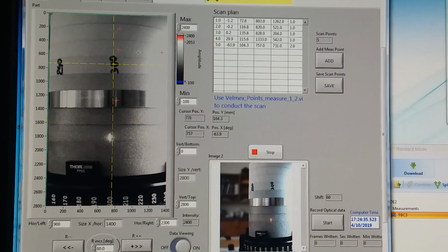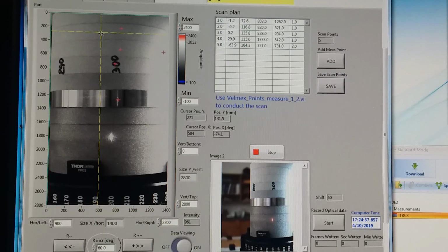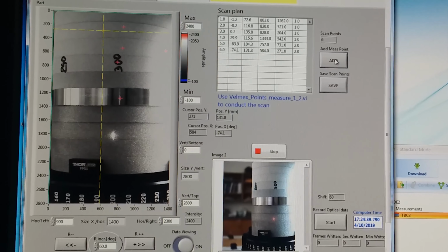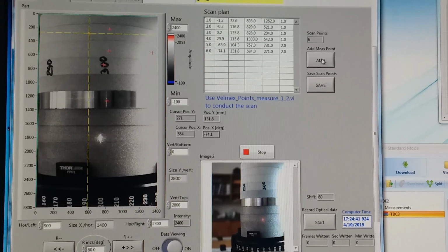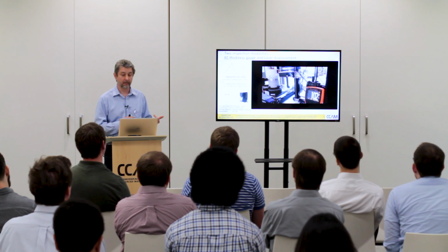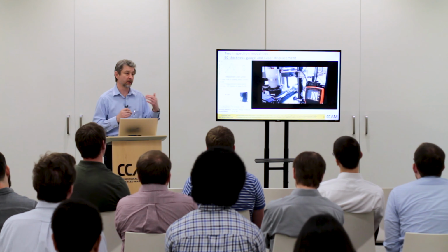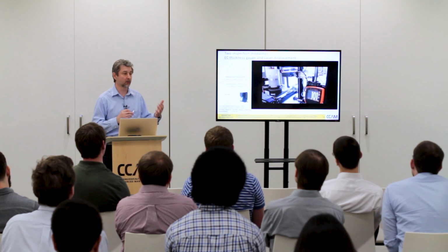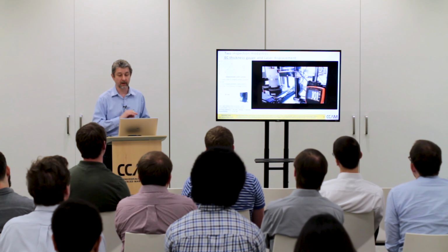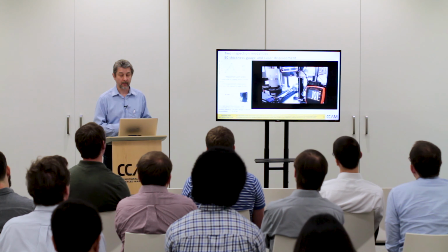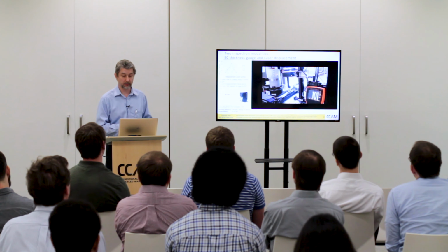Here you see the thickness gauge reading in microns on the bottom right. The variations are in the range of 1 micron over different repetitions, but we certainly measure much larger changes, about 20 to 30 microns of increment from one to two to three passes over the part with a plasma spray coating.